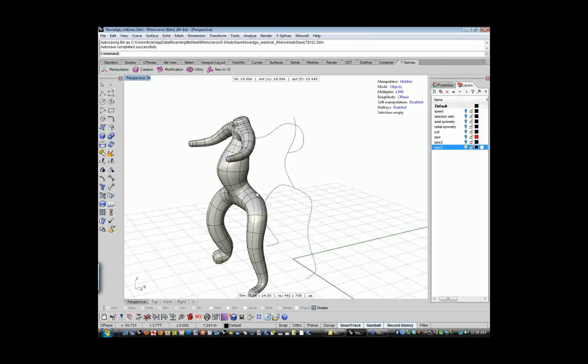One quick note about history too. I just want to put this idea in your head. I'm a big believer in clip art libraries. I create hundreds and hundreds of models a year, and I'm always looking for little bits and pieces from those models that I can stick in a file and repurpose later. Say you're an eyewear designer: you can create a frame profile using curves and the pipe command, save that off as a piece of clip art or a library item, and bring it back at a later date next time you have to do frames, and your frame is already there.